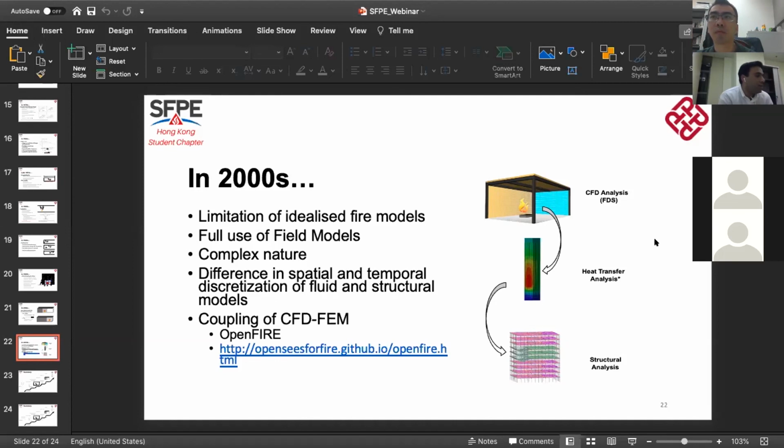Yeah, actually for this one, as I said, CFD is very sensitive to any parameter. So you have to be very careful when you're using CFD about what parameters you are using. Maybe you are not representing the model very clearly. That's why your temperatures are different. And as I said, the engineering fire model also has some limitations. So there's a difference both ways.